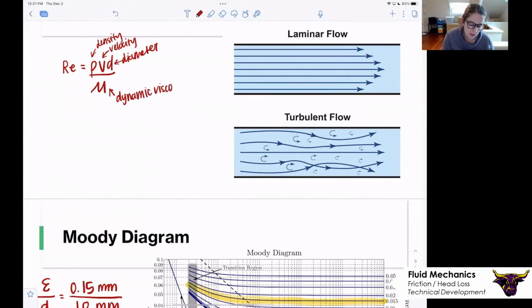And all viscosity is, maybe you've heard the term, but not really known what it meant. We think of corn syrup being a viscous fluid, whereas something like oil or water is a less viscous fluid. What that means is the dynamic or absolute viscosity of a fluid is the internal resistance to movement of one layer of that fluid over another.